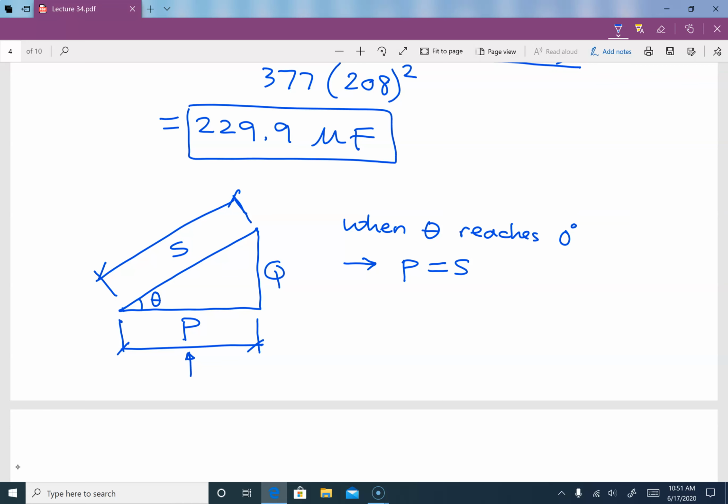So that's why when we correct the power factor, let's say to be unity, then our P and S are equal, which means that you are maximizing your benefit out of that, let's say, energy consumption. Clear? I hope that message is clear.